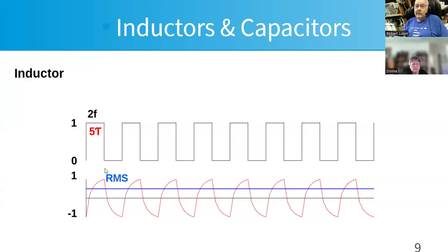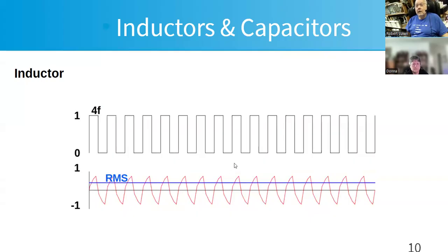So when we double the frequency, we have only half as much time to charge it. In this case, we're just getting to full charge. And the RMS is a little bit lower. I double the frequency again, and see now it's only partially charging. And when you look at the RMS, which is just flipping these negative portions up here and essentially calculating what the area under the curve is, you can see the RMS is dropping, has a less effective voltage or current, I should say.